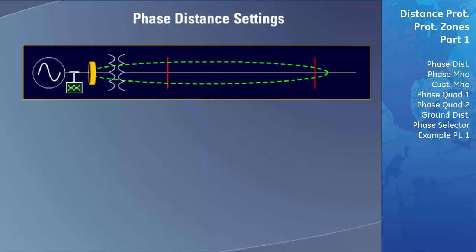transmission line. In our power system example, the transmission line is separated from the source with a delta Y30 power transformer. Both the CTs and the VTs are also separated from the transmission line by this transformer. In this case, we will need to configure in the D60 the phase shift of the CTs and VTs from the transmission line. In the transformer voltage connection field, select the type of transformer being used and its relative position